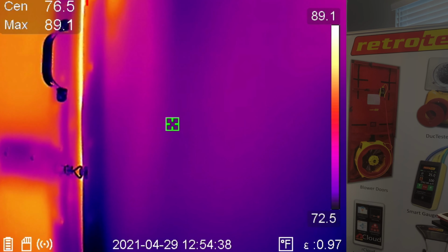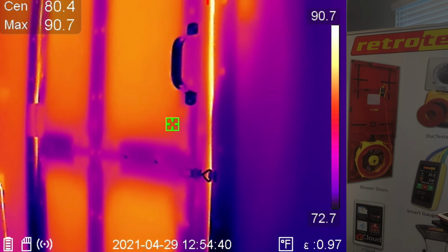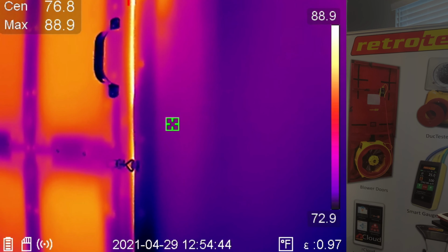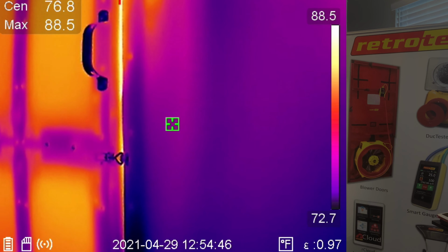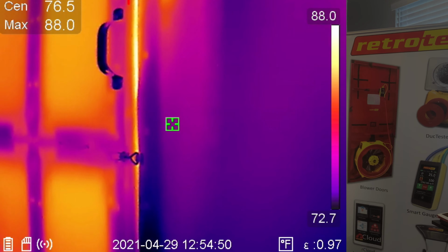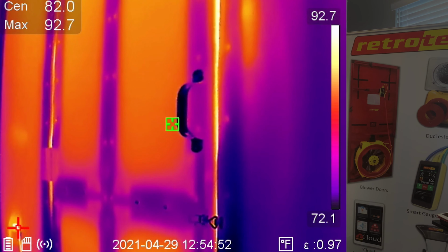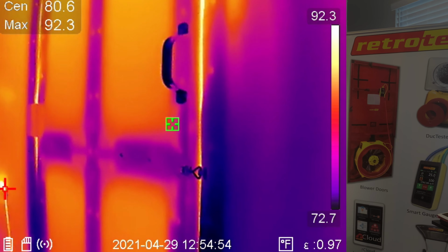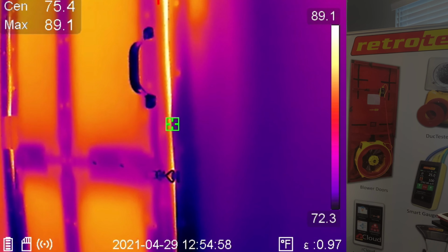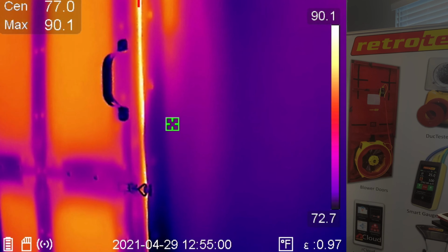If you do this long enough, you'll definitely be scanning some rooms, exterior walls, ceilings, and floors, and you'll see spots like this that don't have insulation. Whether it's from some kind of repair in the ceiling where insulation got moved or didn't get put back, or maybe a stud bay got skipped. Every now and then you'll come across that.